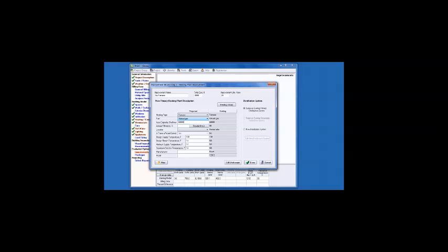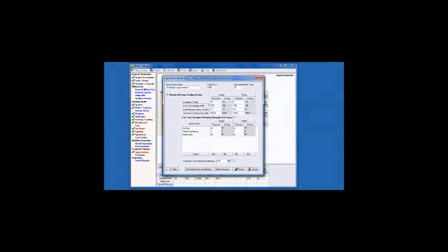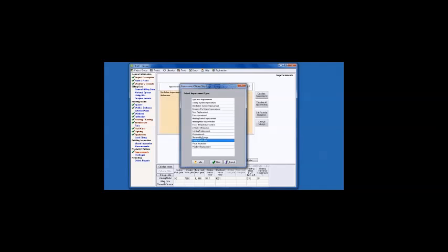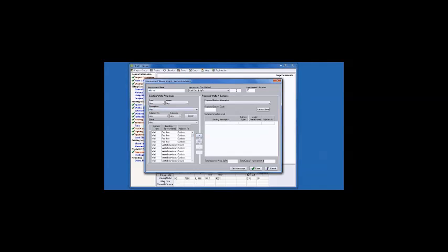And a condensing furnace located in the same place. We capture the new make and model information, and let's say we're going to improve that ductwork for $1,000 while you're up there in the attic. Really insulate it and really seal all those big holes, and maybe you're also going to insulate that attic while you're up there. Maybe it's $2 a square foot because you're going to really fill it up with cellulose.